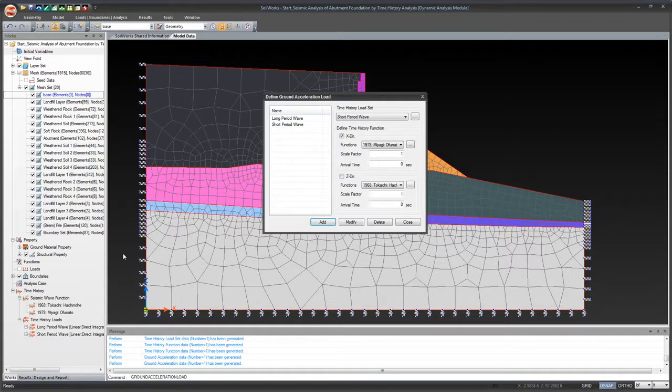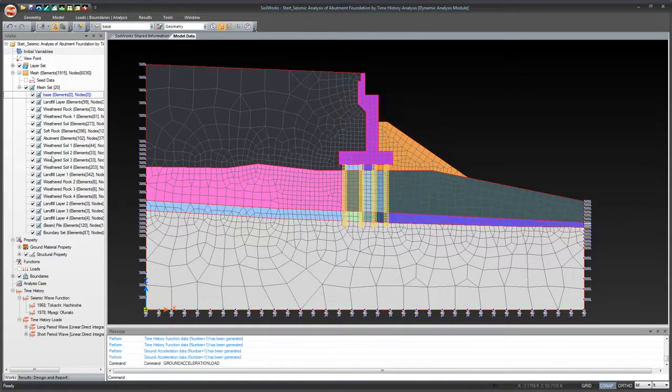Okay, so it's really important. Whenever you're doing any sort of project, this is very key: make sure that all of your material properties and all of your loadings are in black. If one of them is in blue, that means it's currently not in use. You need to go back and see how to assign it. The only thing that can be in blue is the base here, which is just a default mesh set, which if it isn't actively in use, is all right, as long as the ones below it are. So that's another important thing to check for.